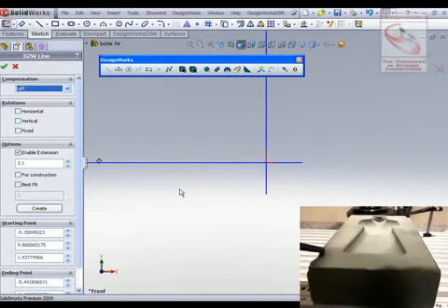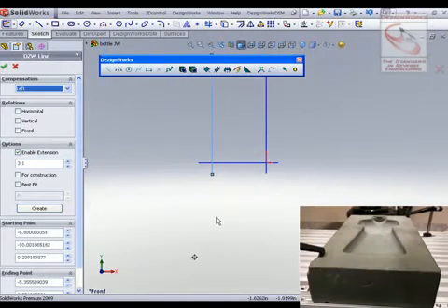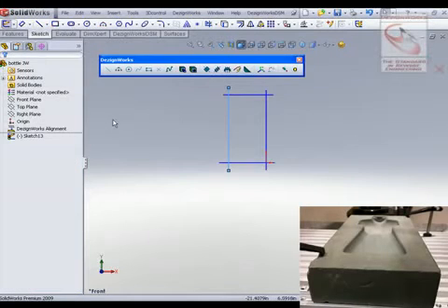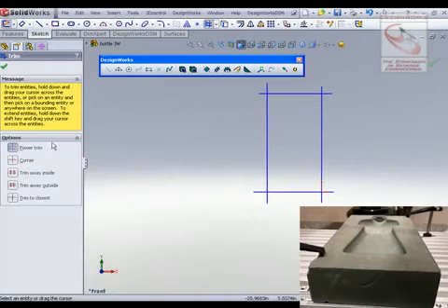saving you time. So all we're going to simply do is take points along this part. It's actually going to create your lines for you. We can jump right into the SolidWorks trim tool, and like we talked about before, because we enabled the auto extend, we can do a power trim. Come over here and actually trim this off, saving you several extra clicks.